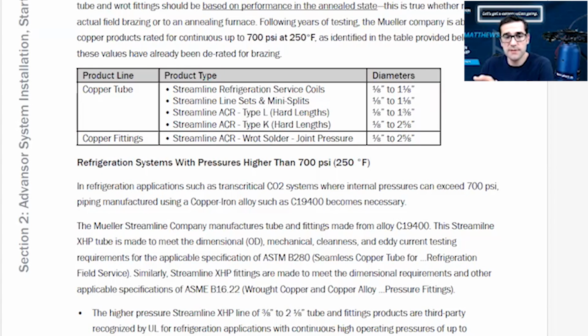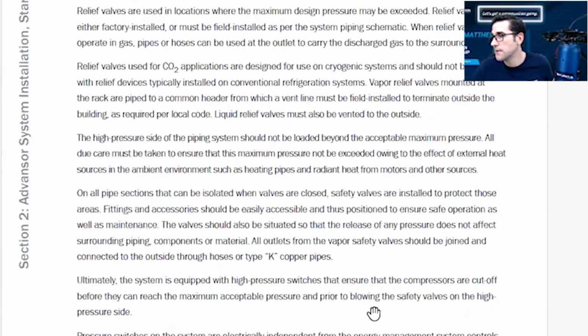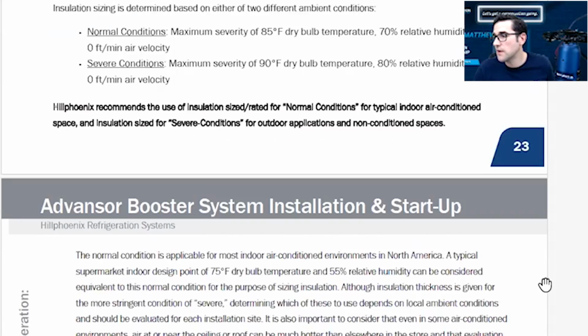And another big thing is the fittings. Understanding those fittings that you have. Are they the right fittings? You don't want to take K fittings and add them on to a high pressure system. They do look different. They feel different. The high pressure ones are heavier. You have to keep that in mind. Don't be mixing up those fittings for sure. That's very important.